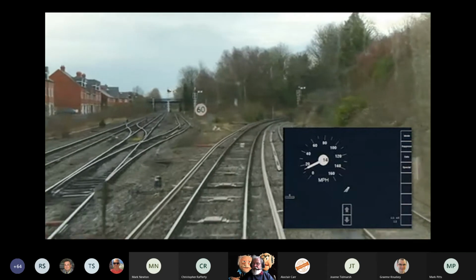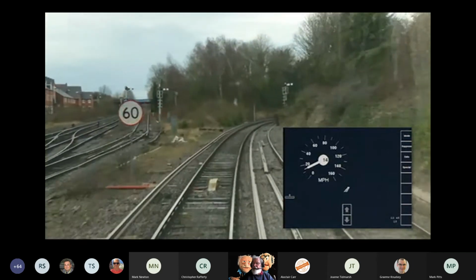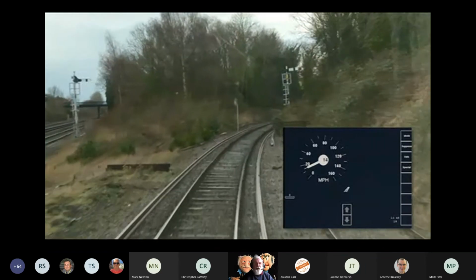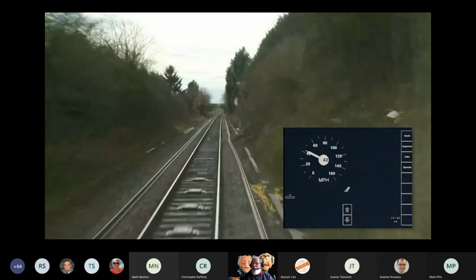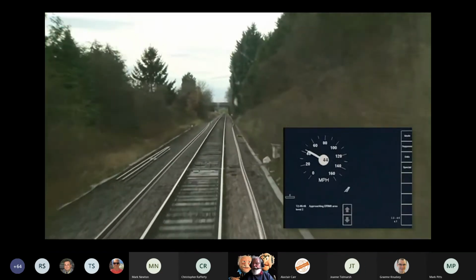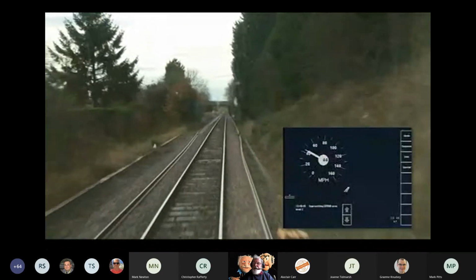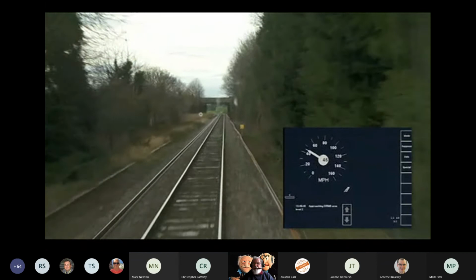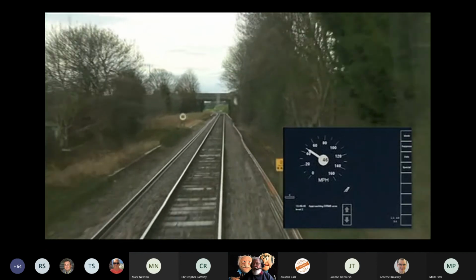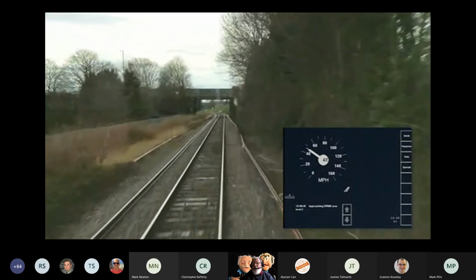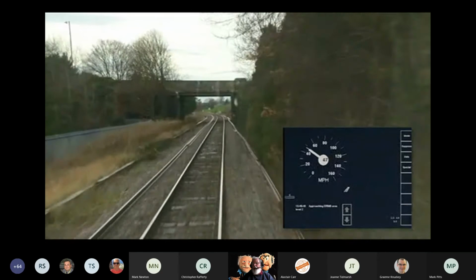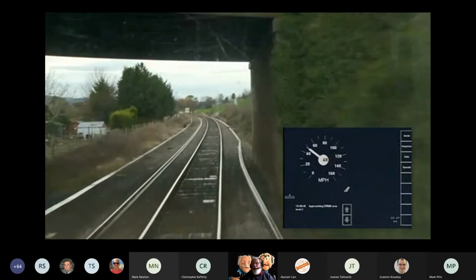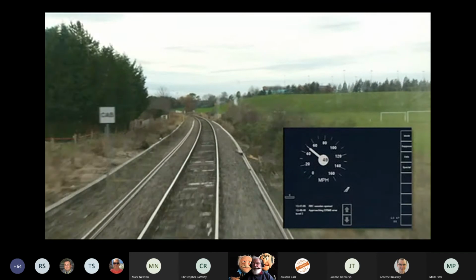As the train approaches the transition, the first thing is it reads a set of balises, and those balises are instructing the train what radio network to use. As the train proceeds, it then gets an instruction to connect to the relevant RBC, the radio block center, and that communication enables other things to happen, and that can take some time. So there is typically a 40-second allowance.